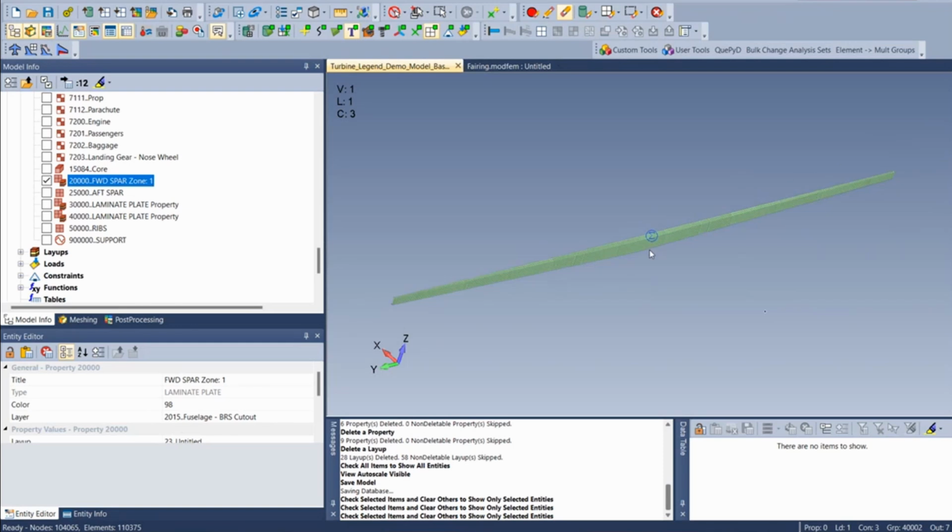Well, in the past, when we would define these zones, you might have an Excel spreadsheet. We typically will size our wing spars just by basic Excel calcs initially. You would have to literally create, okay, well, I need PCOMP 1 here, property 2, 3, 4, 5, 6, 7, 8, 9, 10, 11, 12, 13, and you end up trying to manage that.